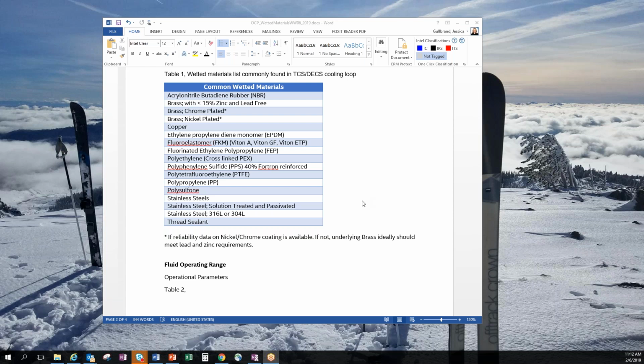But in OCP, I don't think that we want to limit the type of cooling fluids that we're using, but rather allow different types of cooling fluids. When I say different types of cooling fluids, it's really water-based with additives, propylene glycol water, and dielectric fluids. So I'm hoping to get information from fluid suppliers as well, to share what design considerations you need to take into account when thinking about the different fluids.